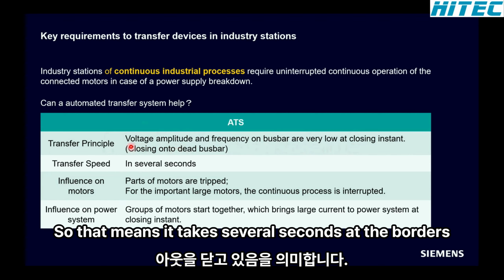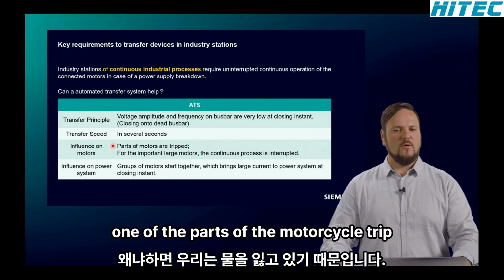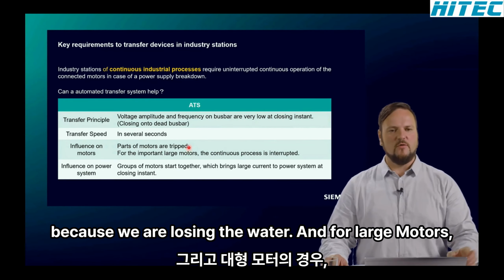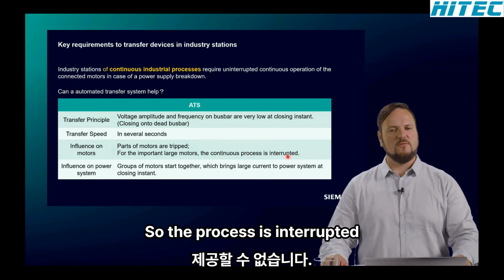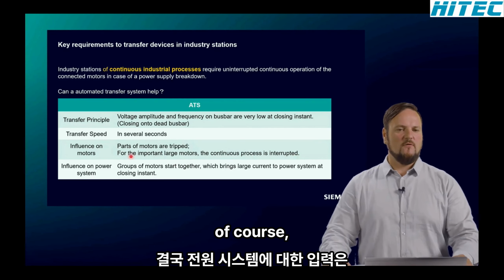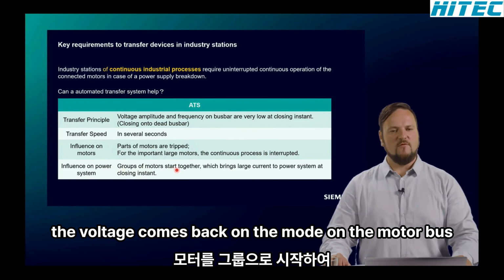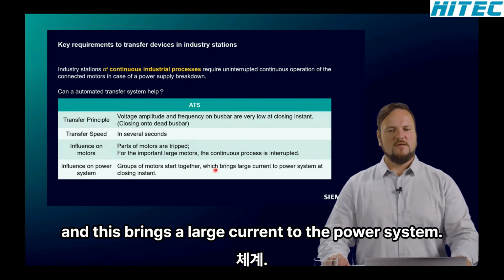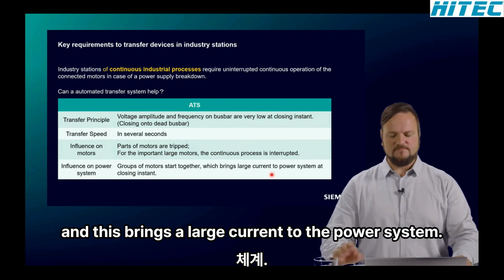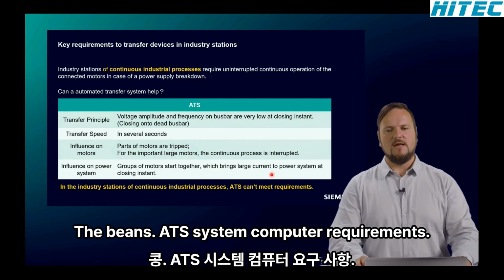That means it takes several seconds and the voltage goes down to 0. And of course, some of the motors are tripped because we are losing the voltage. For large motors, of course, we cannot provide a continuous process, so the process is interrupted. And in the end, of course, the influence on the power system will be that after the voltage comes back on the motor bus, we start the motors in groups, and this brings a large current to the power system. So that means a normal ATS system can't meet the requirements.